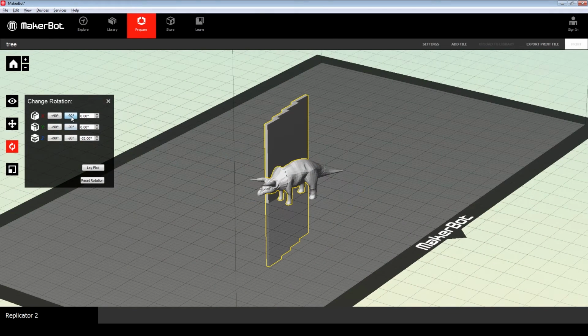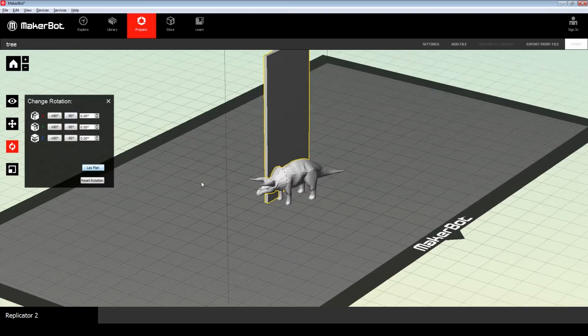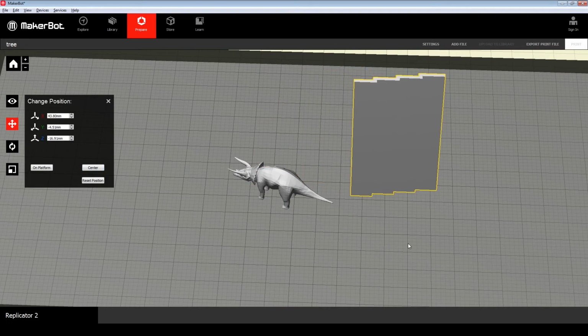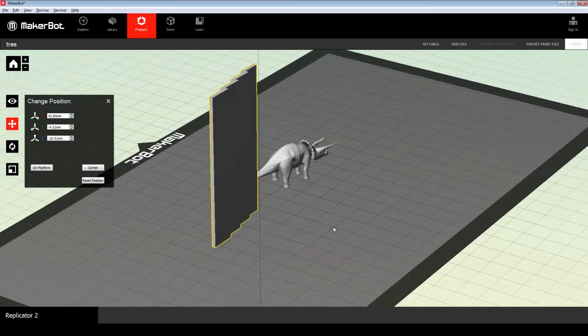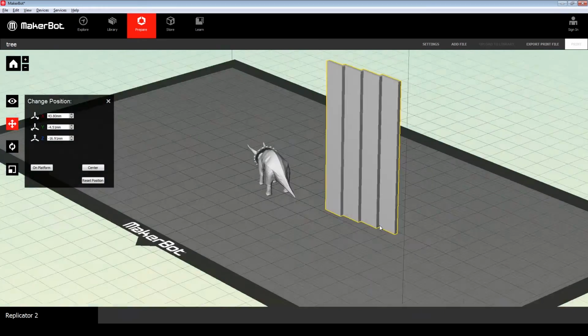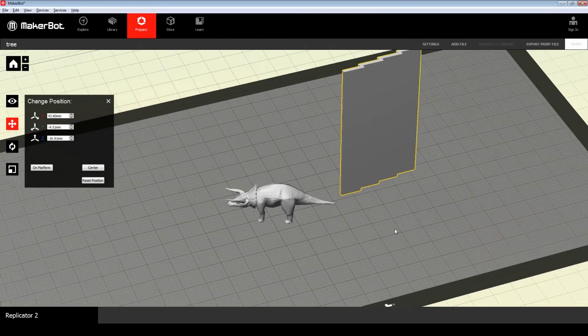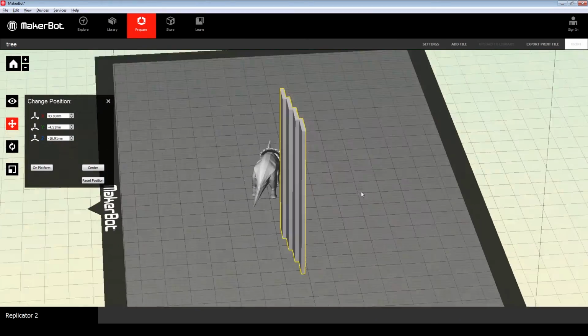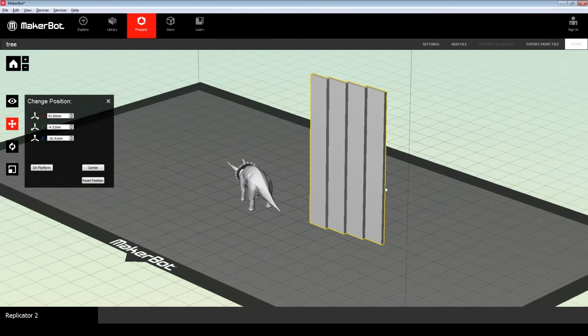And then I'm going to stand them up on edge and run Lay Flat. And then let's move them to the side just a little bit. So again, printing something like those steps edge up is both going to print quickly, it's going to print accurately, and you're going to be able to do that without any supports. Really simple system to get that working.